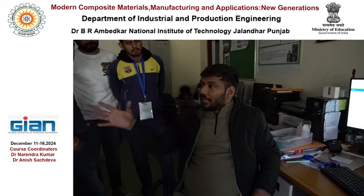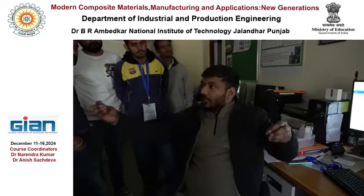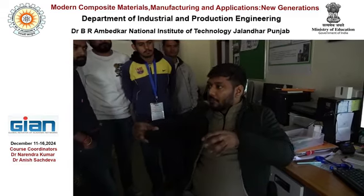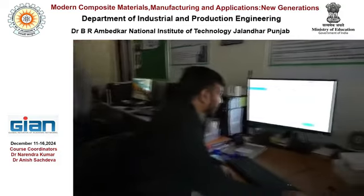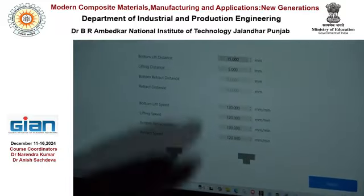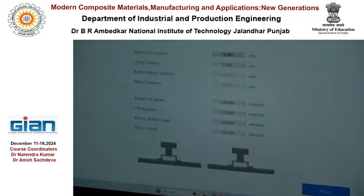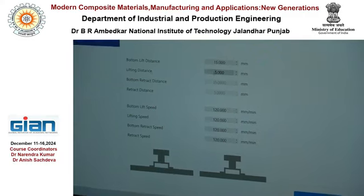If the viscosity is high, you have to lift the platform a little higher, because high viscosity material will take more time to fill the gap between the platform and the surface. So 5 mm is the bottom lift distance. If we increase it to 15 mm, you will see each layer printing. So bottom lift distance 15 mm, lift distance is also 15 mm.